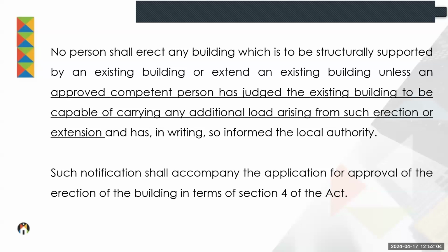So if you do alterations and additions, and you do not submit a report from an engineer, an assessment report, not a Form 1 or 2 or 3 or 4, an assessment report where the engineer has put down his observations on paper and has concluded that it will not affect the existing building, then what you have submitted to the local authority is insufficient in terms of legislation.